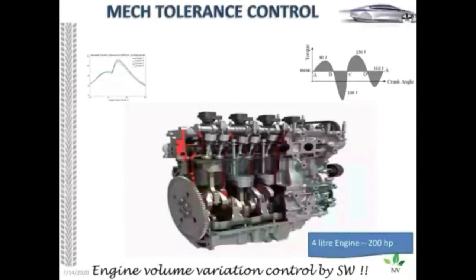So, is engine volume variation controlled by software? We can say software cannot go and change the volume of the engine. This is very clear. It can only aid something; how will software go and increase the volume of a mechanical component? For example, a slightly higher from 1 liter, for example, the second cylinder has 0.9 liter because of a tolerance, 1.1 liter, 0.95 liter. It keeps on varying between the production tolerances based on that. So every day each engine will have different combinations.